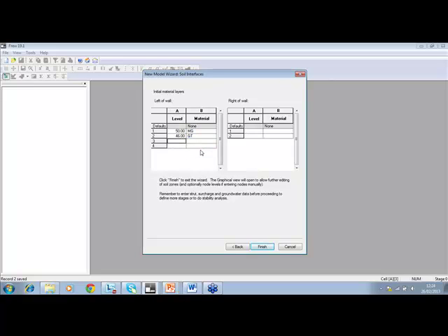And it's very important that you tab through here, because then it registers these things, otherwise it doesn't, and you'll have to go into the tabular output once you get out of the model wizard. 46.5 for the top of sand and gravel. There's a very small sand and gravel level there. And 46 meters for top glacial till. Finish.